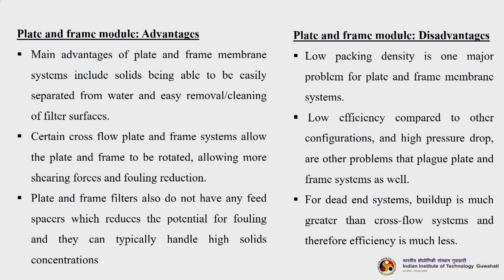So, the disadvantage is that low packing density is one of the major problems, along with low efficiency compared to other configurations and high pressure drop. Other problems plague the plate and frame system as well, and for dead end systems, buildup is much greater than in cross flow systems and therefore efficiency becomes lesser.